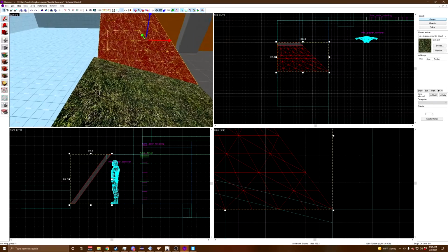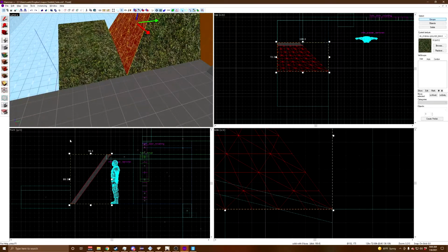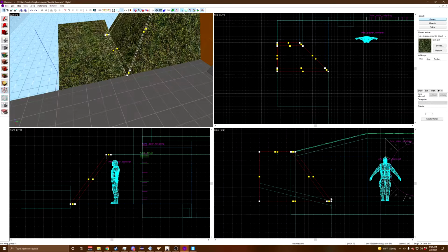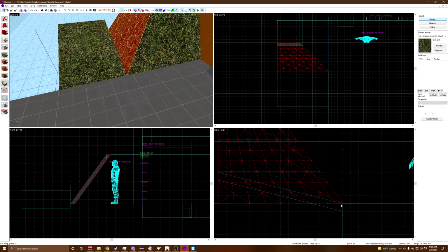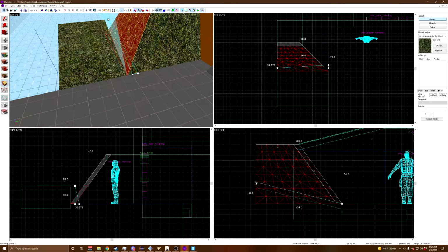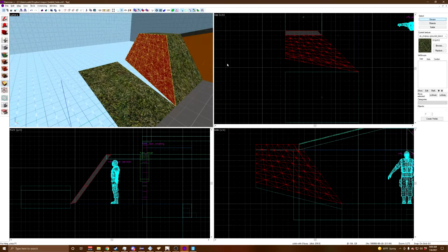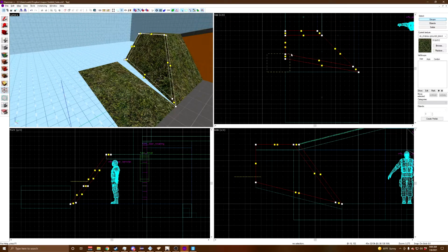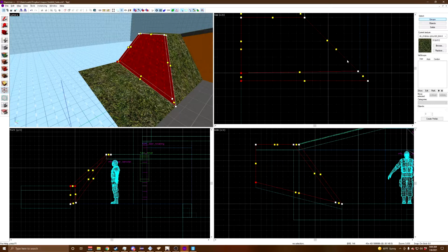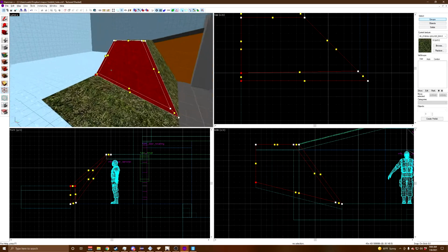Only problem here is, unlike the 45-degree angle one from earlier, we don't have an easy way of getting this one on the slope. So let's undo those changes, and instead of using the vertex tool, let's use the clipping tool instead. Drag a line from the bottom of the ramp to the top, and delete the unnecessary bit. We're not quite out of the woods yet though, because if you've noticed, this isn't sewable, and we can't just use the vertex tool to make it sew. Trying to fix the gap with the vertex tool will only reintroduce the invalid solid.